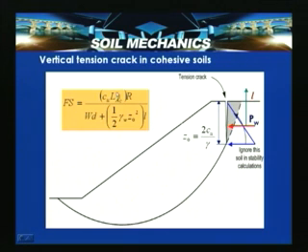So, the factor of safety is the resisting moment, that is Cu into L into AC. We need to consider in this zone the weight of the soil, and the extension of this portion of the failure surface has to be ignored. So, ignore this soil in the stability calculations, and also the length of the arc extending into this portion should be ignored. That means after knowing the depth of the tension crack, pointing it on the surface, once your circle and slip surface are located, you need to find out the actual length which is involved.